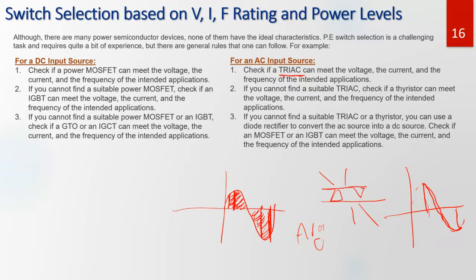The reason is that old dimmers would introduce a lot of harmonics, and the harmonics could damage electronics in your house. But nowadays they have a bit of filtering and other components that take care of the harmonics.